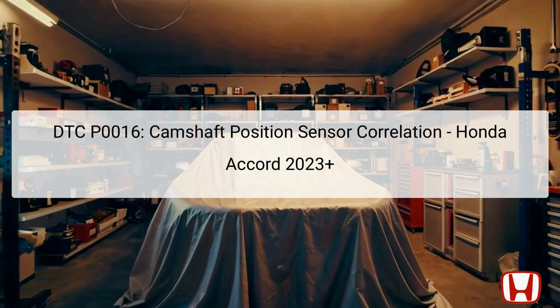The Diagnostic Trouble Code, DTC, P0016 indicates a correlation problem between the camshaft position (CMP) sensor A and the crankshaft position (CKP) sensor. This DTC is significant as it affects engine performance and can lead to various operational issues.